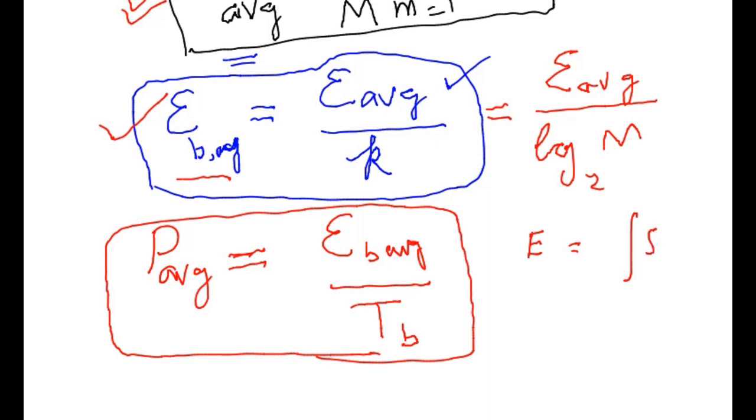If you have a signal s_m(t), the energy is the integral of s_m squared of t dt. This is the broad definition, where the limits are from minus infinity to plus infinity. But when we are talking about a signal which exists from 0 to T, our limits change from 0 to capital T. This is the symbol duration. This is the energy of our signal.